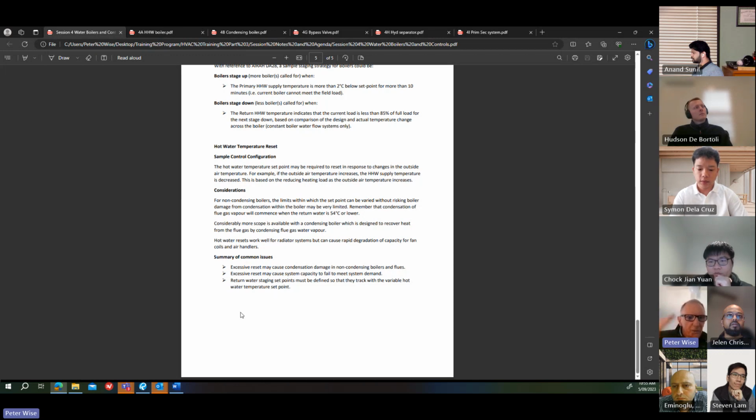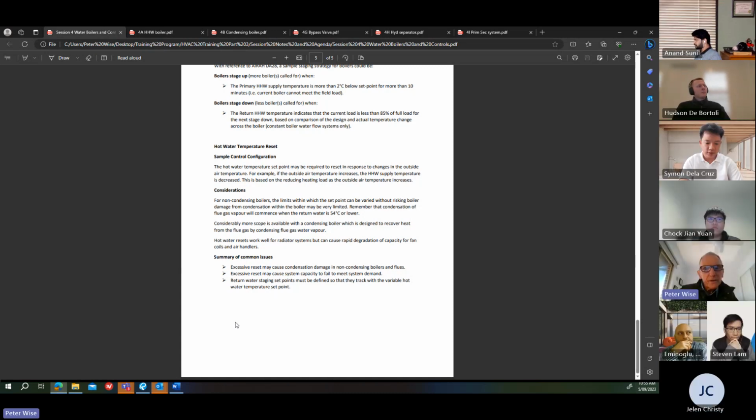But obviously it's going to be in between most of the time. So there is valve authority there, in that you want to restrict the flow through the bypass at part load. Part load is always going to be the critical situation. But the pressure drop will equal the field pressure drop when the valve is fully open. But at that point, if you've got full flow through the bypass, then you don't need the heating system anymore. And that's a trigger to start shutting down the boiler. Does that make sense? Yeah, yeah.